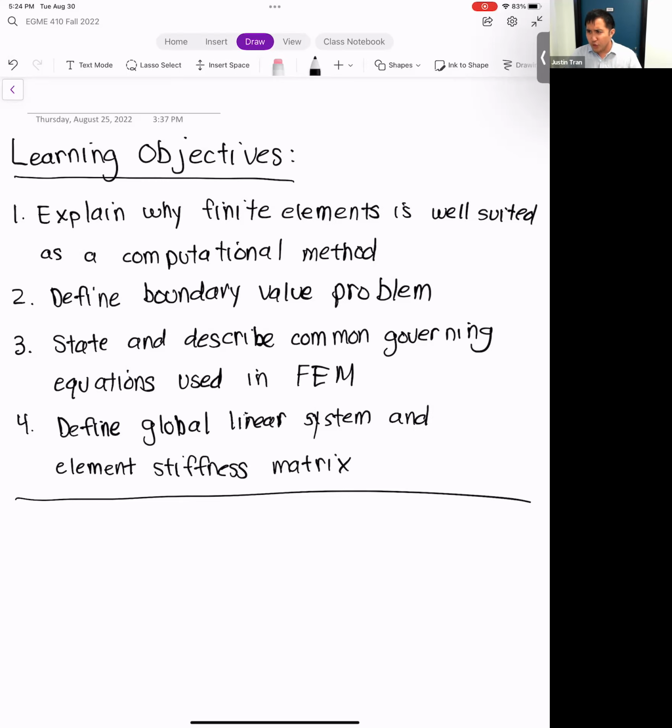Oh, if you want to remove the refinement, just right click the refinement object and just say remove. So when you're in ANSYS Mechanical under mesh, you see that entry in the project outline that says refinement. Just right click it, and then there will be something in the menu called remove. So that's how you do it.